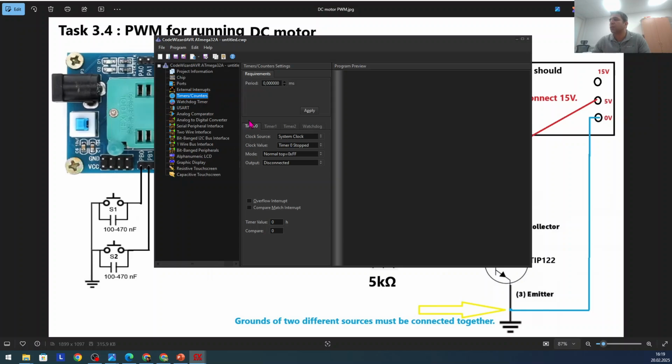So we come here, timer 0 is this one, it's an 8-bit timer. In this one, we wanted to have overflow interrupt and compare match interrupt. These two were needed. And then, this is stopped right now. You want it to work with, what was the frequency we wanted? We want to have a 20 millisecond period for the timer. 20 milliseconds. Let's see if we have this, for example.